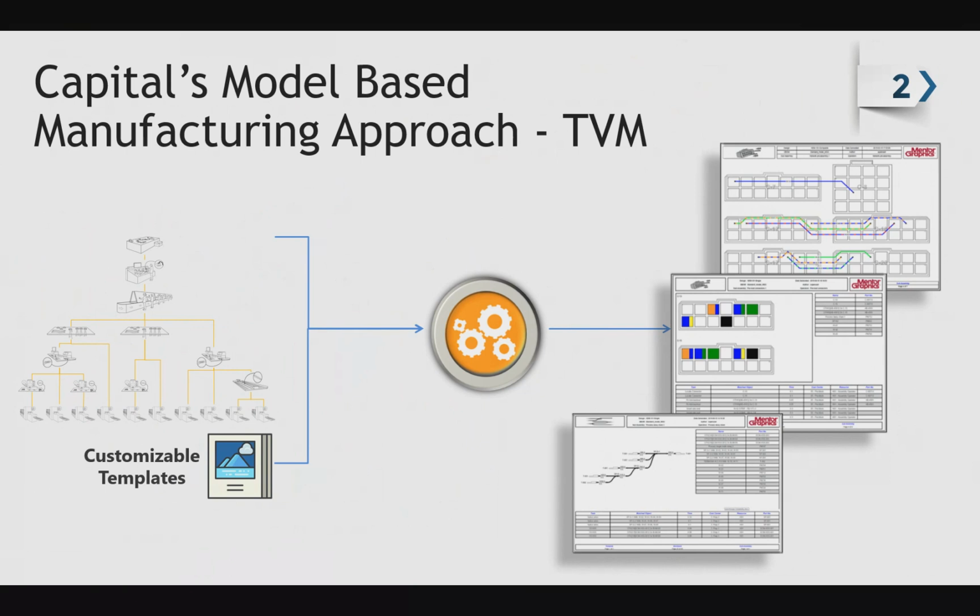Capital Workbooks automatically generates operator work instructions by mapping a digital description of the harness design against the production process model, or pattern as we call it. One or more pages can be generated for each step of the harness assembly sequence. For example, splicing, connector loading, wire twisting, and these include tables, static images, conditional images, barcodes, etc.